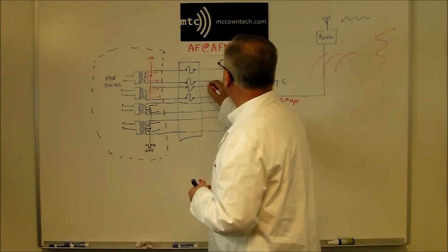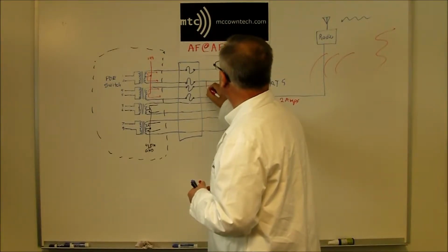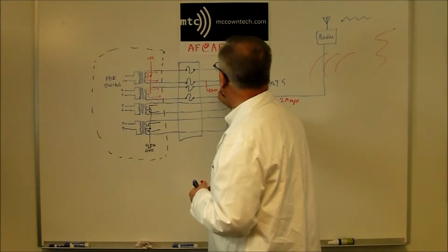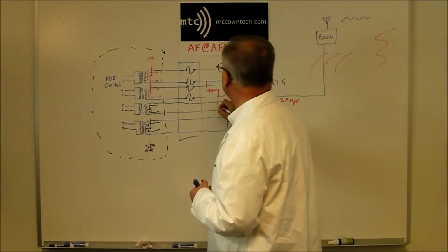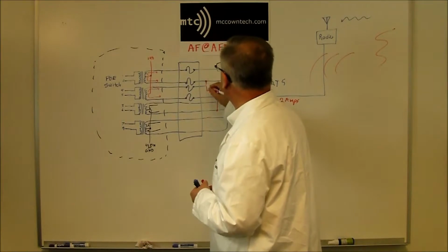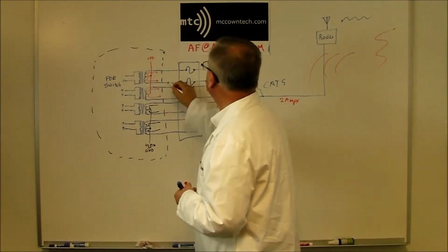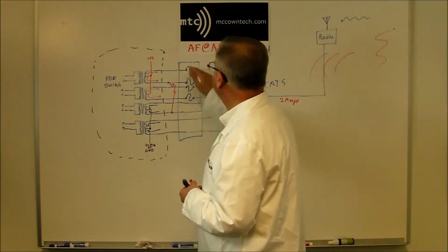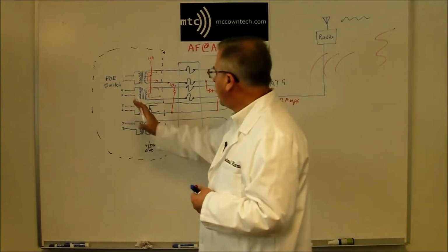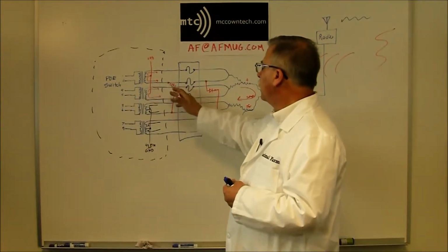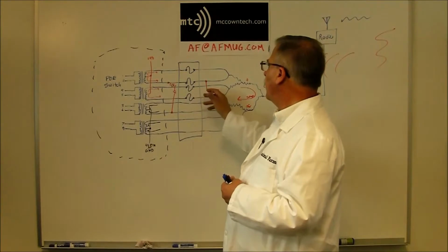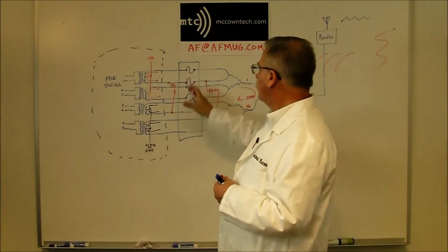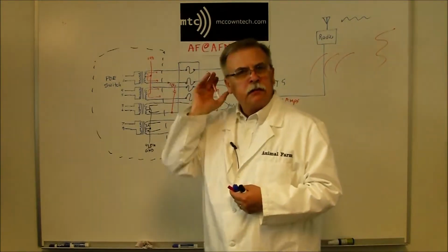So you could put an LED here. Have a hook to its corresponding return. And you put another LED here. Why would you have 2? Well, here's the deal. If the fuse blows and you've got power coming in, this LED will be lit. This LED will not be lit because the fuses have prevented the current from showing up on the other side over here.